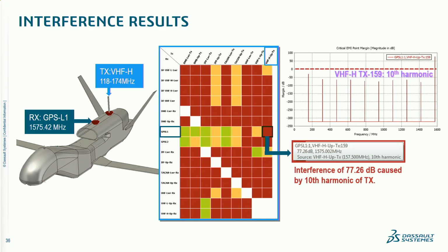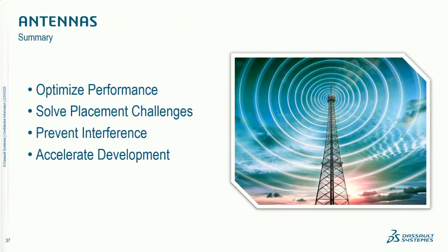And the reason they do, what you're seeing there is an interference matrix, looking at unfiltered performance for all of those. We see quite a bit of interference, but specifically on that one, it's actually caused by harmonics. All of these antennas radiate not just at their intended frequency, but you also get harmonic resonances at multiples of those. And it's the 10th harmonic of roughly 150 megahertz, about 1.5 gigahertz, and we can see issues in there.